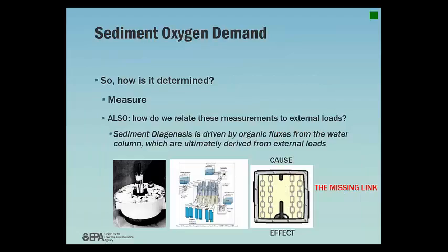One way around this is that we can actually go out there and measure it. There's a couple of different protocols available for measuring SOD. Both are time-consuming and they are expensive. One would be the placement of an in-situ chamber on the bottom of the water, and it measures the amount of oxygen consumed through a time period. Or you could take cores and bring them back to a laboratory and do the same thing. That's how we can measure it.